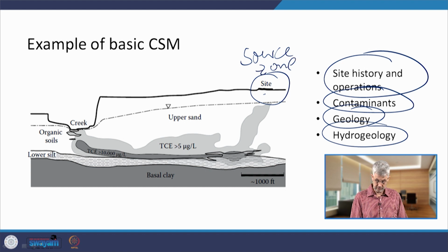Okay, so the contaminant has entered here and has met the groundwater table, whose elevation we probably know from drilling. And then as it dissolves into the flowing groundwater, it forms a plume. In this case, the plume dove to the bottom of the aquifer, forming what looks like a free-flowing product, or a DNAPL, or dense non-aqueous phase liquid, the appropriate term.